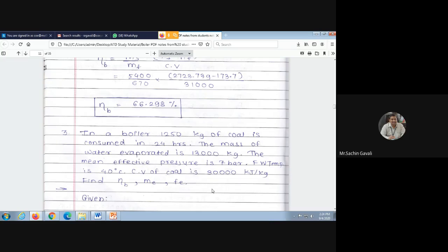Okay. So here, as dryness fraction is not given and steam temperature is also not given, then we have to assume that steam is completely evaporated. Means water is completely evaporated, no dryness fraction. So steam is dry and saturated. So write down that first.